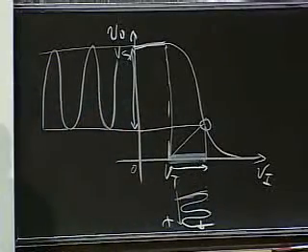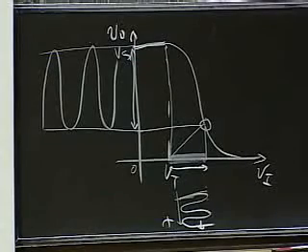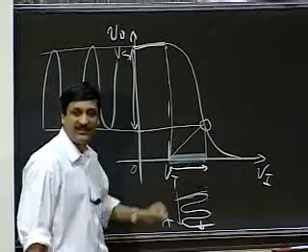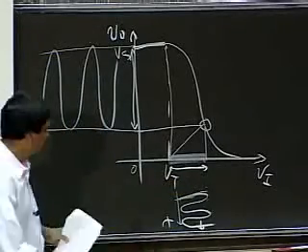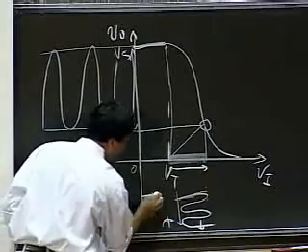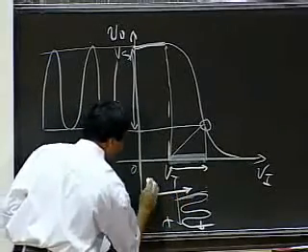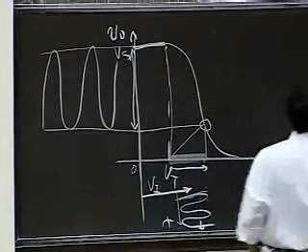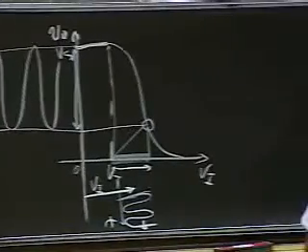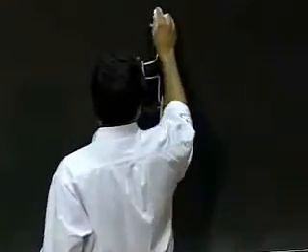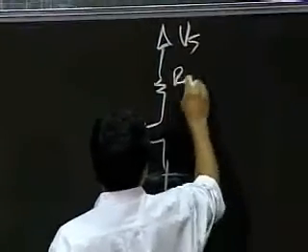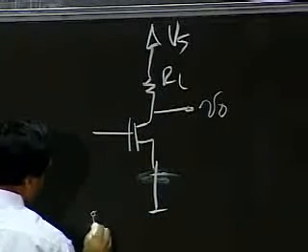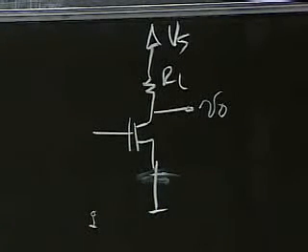So let's have a sinusoid. Okay, let's have a sinusoid that's 1 volt peak to peak or whatever. How do I get my sinusoid up there? Well, you've learned the trick on how to boost things. Remember boost? So all you have to do is boost up your signal by some value capital VI. Okay? And the way you do that is as follows. Vs, RL, V naught. So what you do is you apply a DC offset to your input.